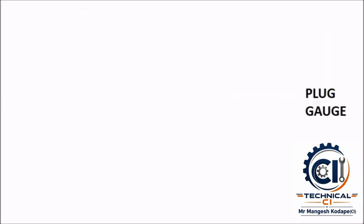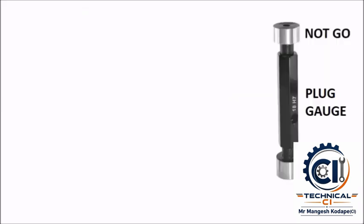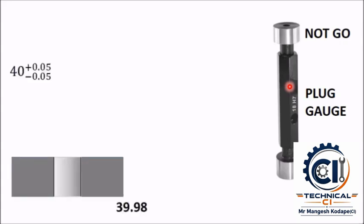Now there is another gauge which is called the plug gauge. It looks like this. It has two ends. One end is the go gauge and another end is the no go gauge. As I explained before, the go gauge corresponds to MML, maximum metal limit, and the no go gauge corresponds to LML, that is least metal limit. Now again I have taken an example of a workpiece, a plate having a hole diameter of 39.98.